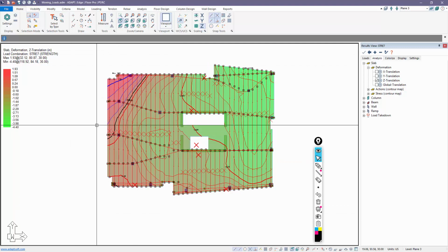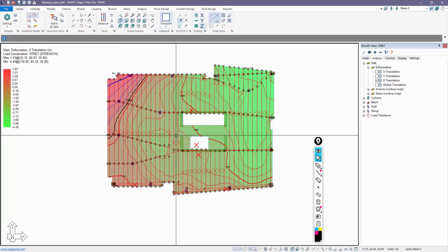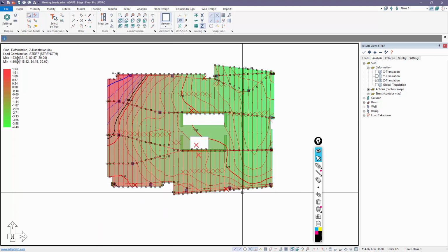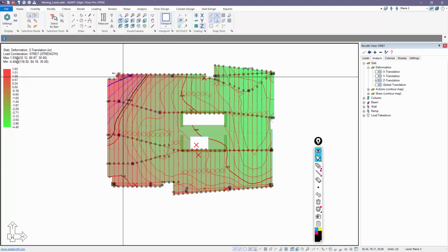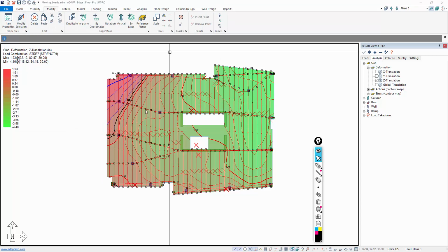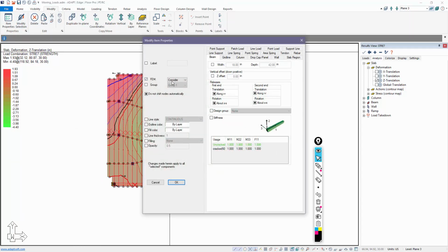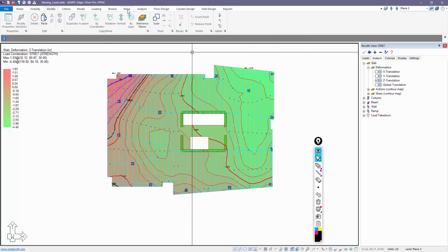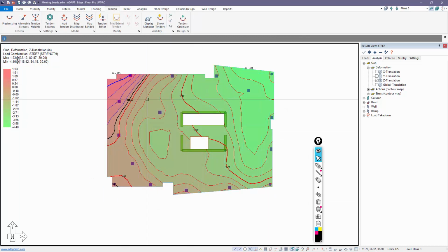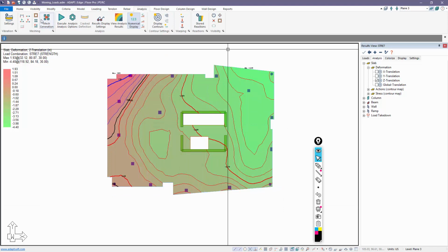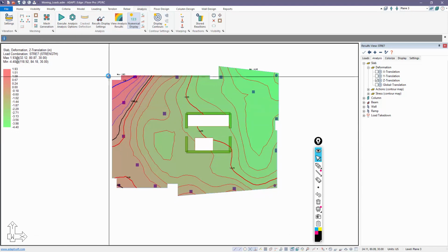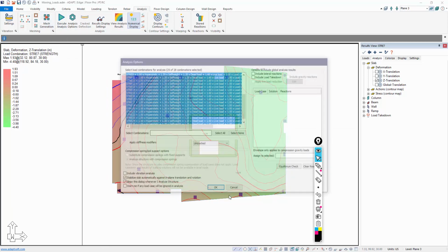But because this is a specialized case, hyperstatic or secondary only, you get this deflected shape. So it's not unique necessarily to this model. It's unique to the way we solve for hyperstatic actions in the software. So we'll take that, we'll modify, and I'm going to just ignore the tendons for this model. That should help us evaluate these deflections more precisely by using the right set of load cases within the combination.